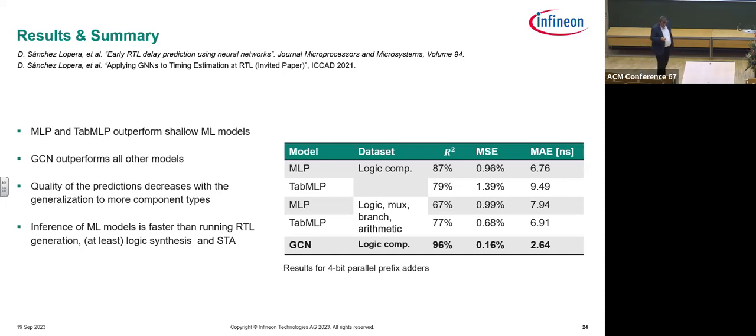And of course, the inference of the models is much faster than using RTL. Now the question is, hey, you're just having some blocks, why do you use machine learning? Because machine learning is a good application if you don't know exactly what happens. And what don't we know? How the synthesizer optimizes, especially the boundaries. If you wouldn't flatten boundaries between your blocks, it would be straightforward: make your blocks and put them together and you know the area.